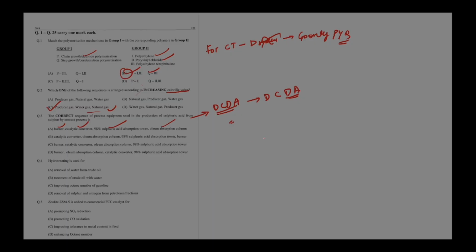The flow sheet of sulfuric acid: very first a burner is there, then a boiler. After that some treatment is there to remove the impurities, then a 4-stage tower is there. It needs interstage cooling because SO2 plus half O2 giving SO3 is a highly exothermic reaction.